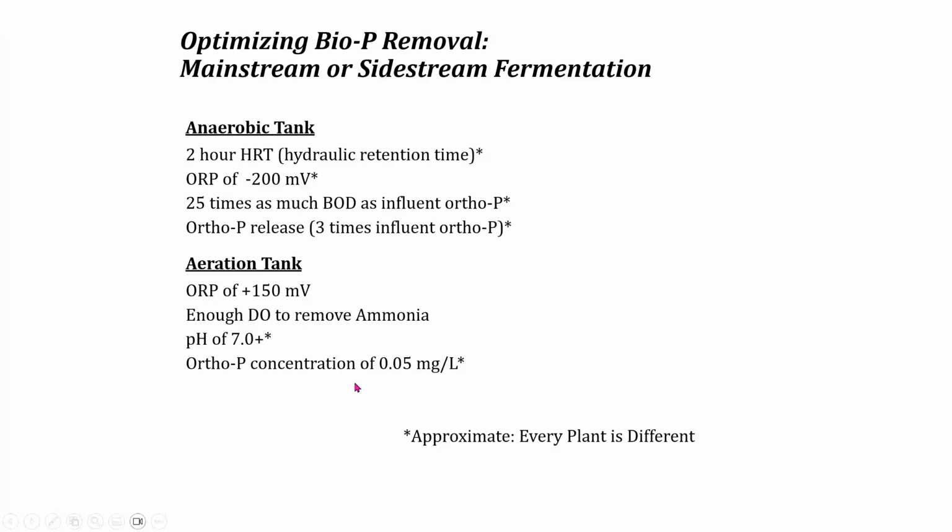And this is pretty interesting here. There's a plant in Tennessee, I might have mentioned it, Athens, Tennessee oxidation ditch, that during the summer months, the phosphorus coming out of the oxidation ditch, the soluble phosphorus is non-detect. I mean, it's below 0.05, 0.02.